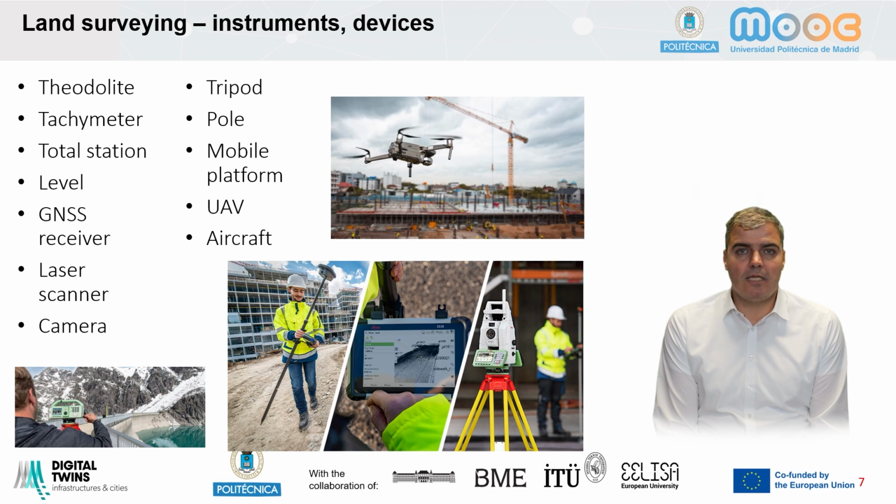In the total stations we are using now on site, we are measuring horizontal and vertical angles and distances. With leveling, we can measure the height differences between 2 points or between multiple points. And with GNSS receivers, with global navigation satellite systems, we can define the geodetic coordinates of any kind of point on site.